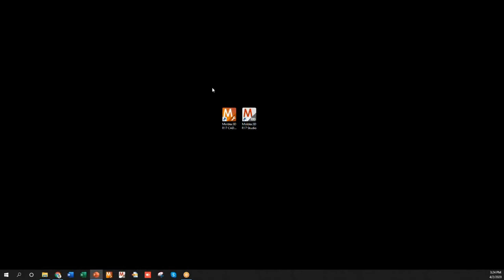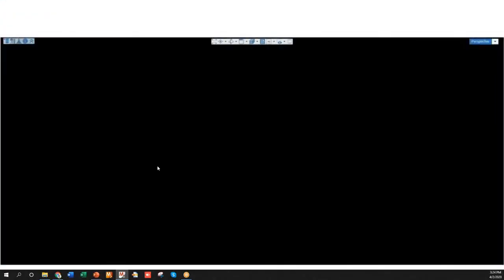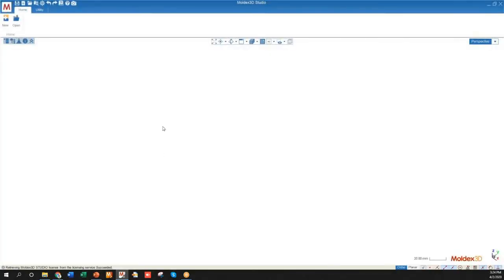All right, now that we've completed CADdoctor, now we can come over into Studio. Like I mentioned, Studio is kind of the all-encompassing application where we will import our model, set up all of our modeling, things like your cooling channels, runners, any inserts. We'll do our meshing, select our material process, and then run the simulation and interpret the results. So this application does everything for us.